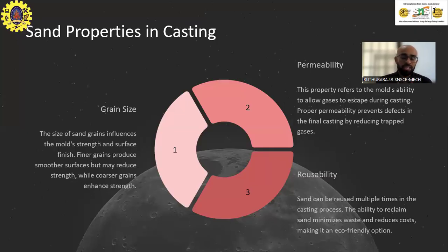But the main application of sand casting is that you have to prepare a mold. So for that, you cannot use desert sand because if you place an object in desert sand and remove it, there will be no impression because it is highly permeable. Then you need the property of clay here. When you place an object on clay and remove it, what happens? The clay retains the shape of the object. So there, the shape retention property is needed.